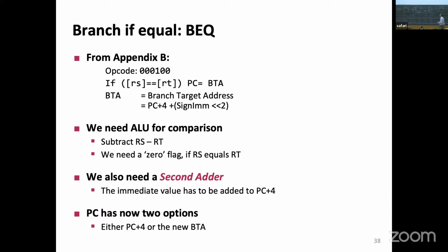Now, what happens is we have actually a similar thing here. At the top, we have a data path. Some of these things are state holding. This one holds state. The register file holds state on the write port. The data memory holds state on the write port. And we have several paths that we can go through. Data flows more or less from left to right, the way that I've drawn. And then there are all these different control signals that select whether I'm taking this input or this input, whether this address is this one or this one, whether the ALU chooses this register or the immediate, whether I read directly the output of the ALU or I read from the memory. I make these types of decisions.